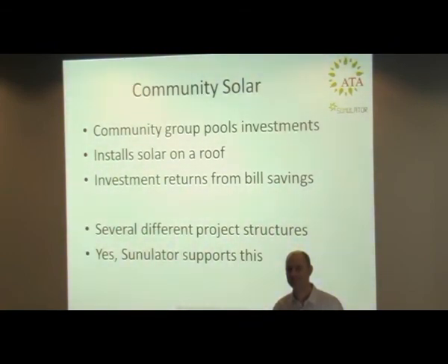The second question on that is, how does it fail? Is it a gradual taper off, or is it sudden abject failure? It's both. The solar panels' output reduces over time, and you can specify that as a separate value year by year if you like. Normally you just say it decreases by 0.5% of the original capacity each year. And then you also put in a cost allowance for replacing the panels, which you can specify your own amount and your own frequency of panel replacement. So it would normally be 20 years or 25 years, something like that.